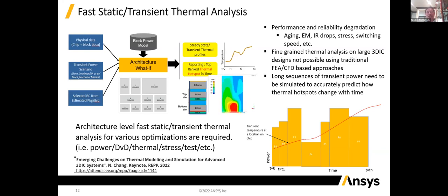And this is a big challenge for the thermal and the stress simulation, because we are seeing that there are 300 time points or 400 time points or even more. And we need to calculate the change in temperature in terms of millisecond resolution. And that will be a big challenge for the finite element method.